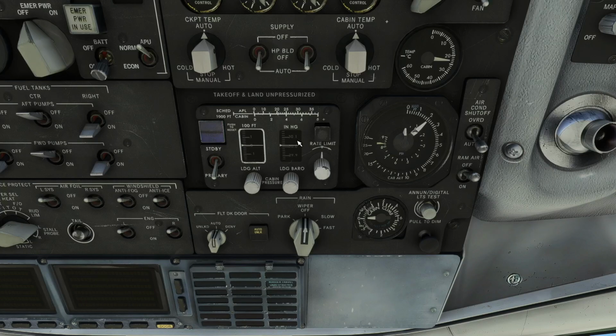If you're setting this to the arrival field, make sure you get the current baro setting for that from the METAR or the ATIS and set it there. The rate limit is for the cabin climb rate. It's in automatic when it's in the bug here, and the cabin will automatically climb or descend if